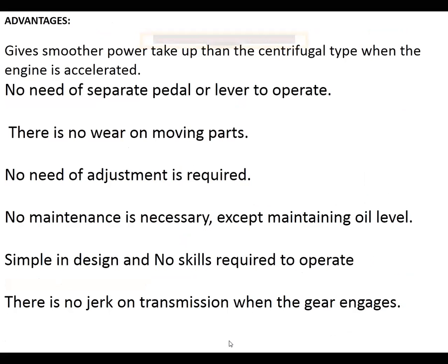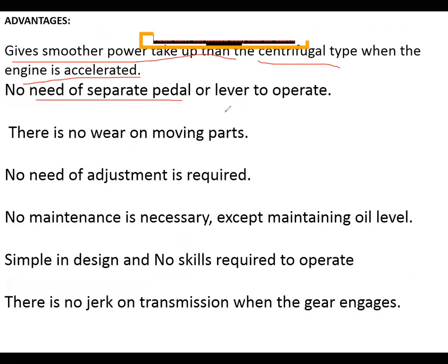Coming to the advantages, there are a few. It gives smoother power take-up than the centrifugal type when the engine is accelerated, right? So there is no need for a separate pedal and lever to operate. There is no wear on moving parts because friction is not produced between the input and output shafts. Fluid is filled between the input and output shafts, so friction between the moving parts is avoided. No adjustment is required.